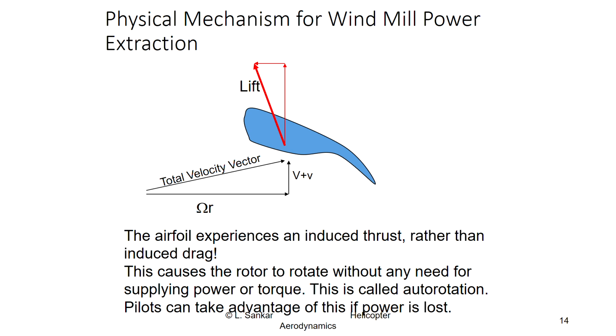Then the forward-directed in-plane component of force will decrease in magnitude, slowing down the rotor. So this is remarkably self-stabilizing. So omega remains stable during the wind turbine brake state when you are vertically descending, and the wind turbine effect is supplying you power.